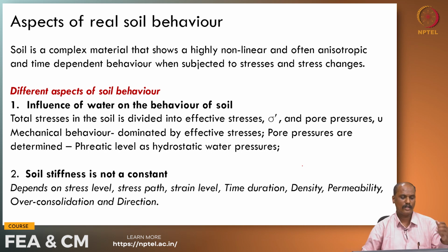Stepping into the aspects of real soil behavior, soil is basically a complex material that shows a highly non-linear and often anisotropic and time-dependent behavior when subjected to stresses and stress changes. Usually these stresses keep changing day by day, or after t equal to 0, t equal to 1, or t equal to n, the stresses are not constant. They are changing with time, so the response of the soils will also change with respect to time.